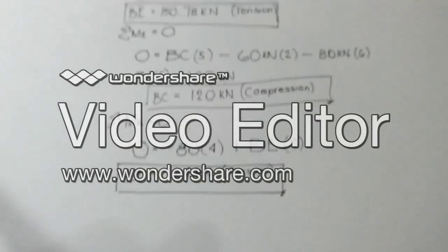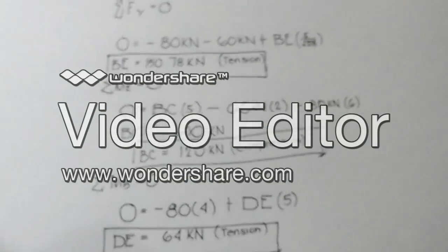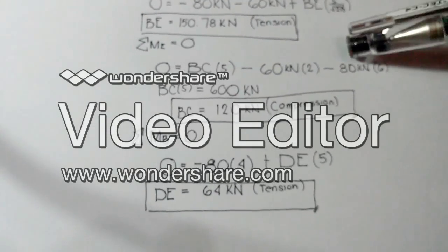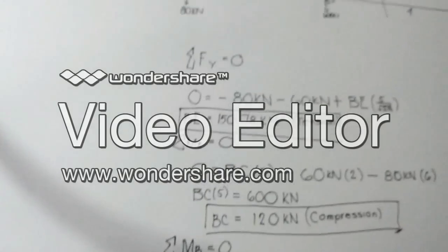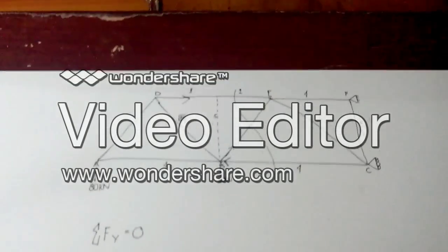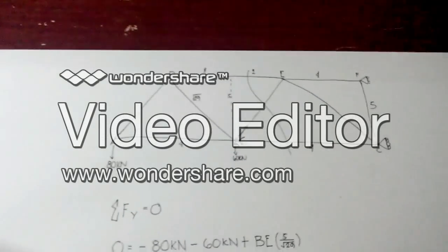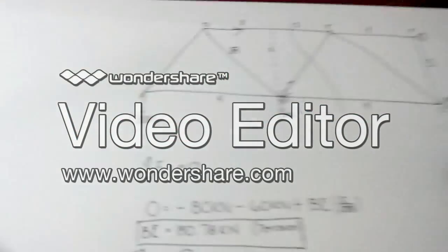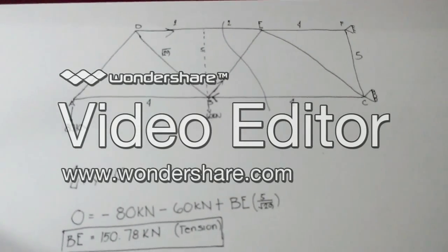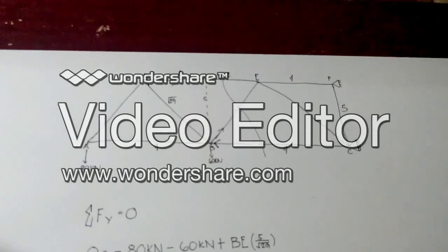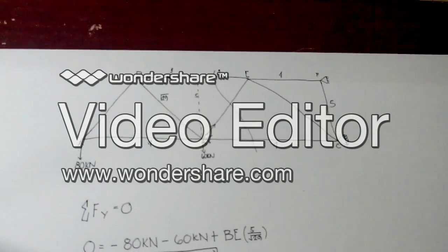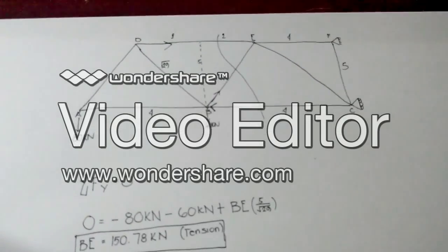So that wraps up, because we have determined BE, BC, and DE. A little tip: you can only cut the truss with a vertical or diagonal plane, and you cannot cut 3 or more than 3 members.